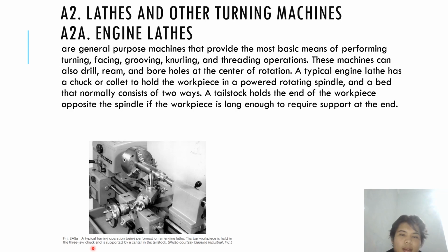Lathes and other turning machines. Okay, we're going to talk about engine lathes. They are general purpose machines that provide the most basic means of performing turning, facing, grooving, knurling, and thread operations. This machine can also drill, ream, and bore. So we're going to talk about that later.